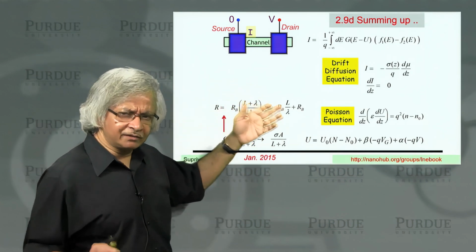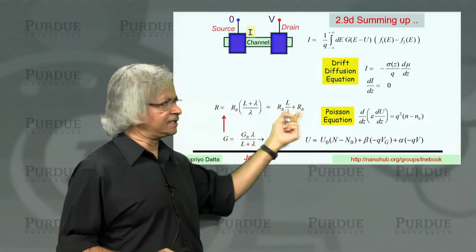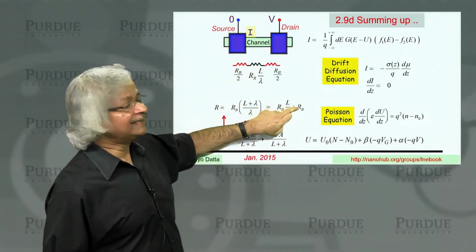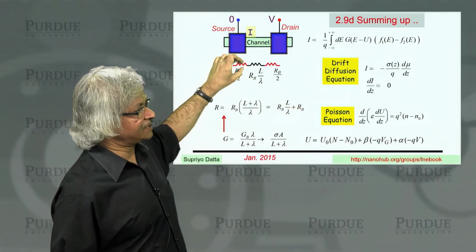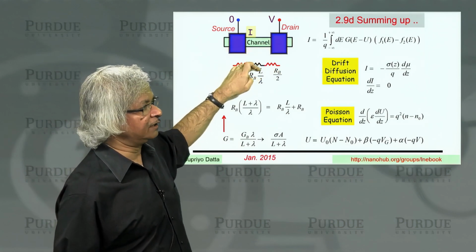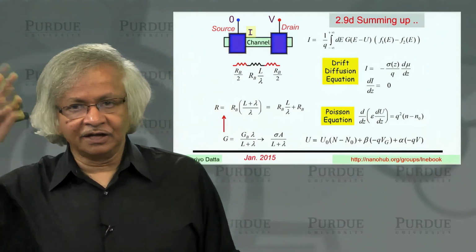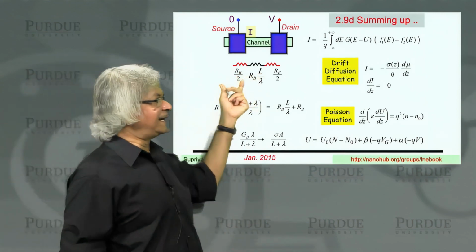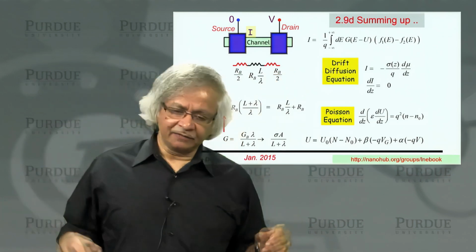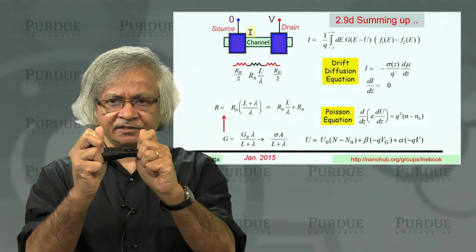But one thing we didn't quite address is what exactly is this resistance? What is it associated with, since it's independent of length? And the point is, the modern understanding is that that resistance is actually an interface resistance that appears at the two ends, whereas the middle part has a resistance that's proportional to L. So the most important thing that this new perspective adds to our old understanding is this idea of an interface resistance. Of course, everyone knows that when you measure the resistance of any conductor, you always have some contact resistance.